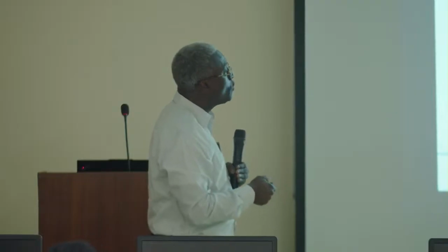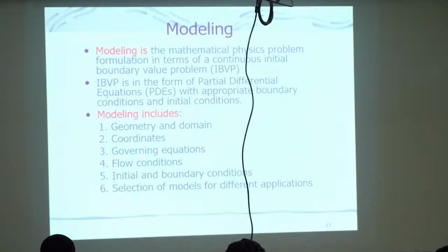You have to understand what coordinate systems to use. You have to understand the governing equations that you have to apply. You have to understand the flow conditions. You have to know the initial and boundary conditions, and then the selection of models for different applications. So every CFD problem will have a pertinent model that is germane to it, that can be applied to it.